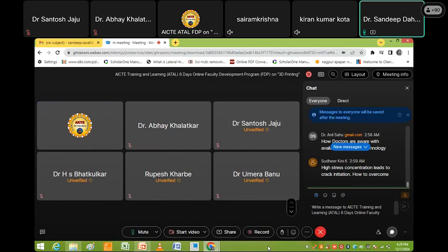I have taken 6 different element sizes and checked the stress results and deformation results. With this range, I obtained similar results, but with the 2 mm mesh size, the processing time is less as well as no error has been obtained. So you can perform this type of pilot study and then decide what to finalize.